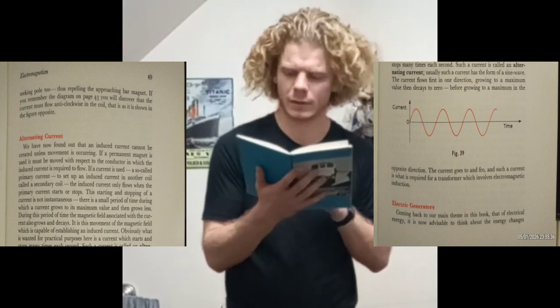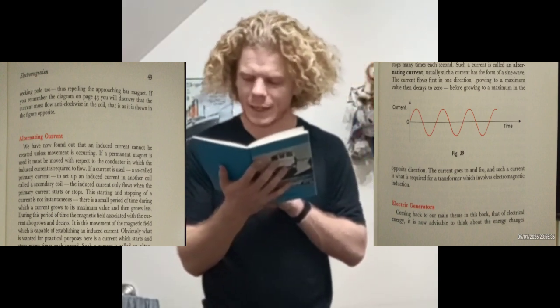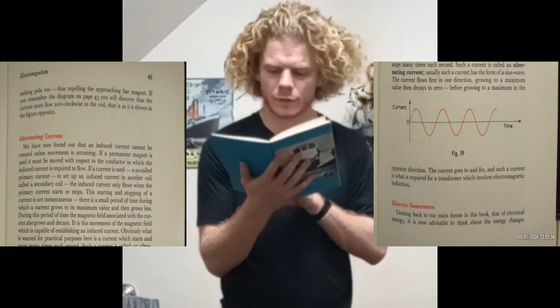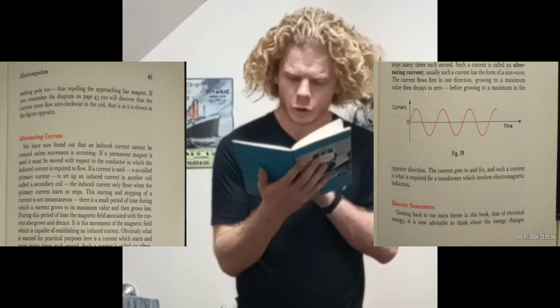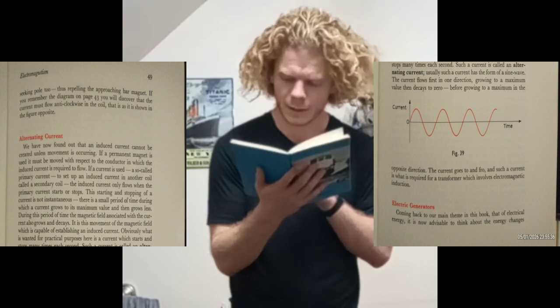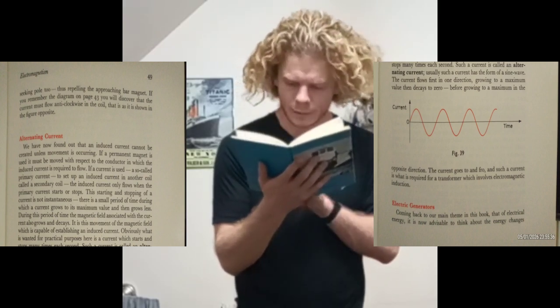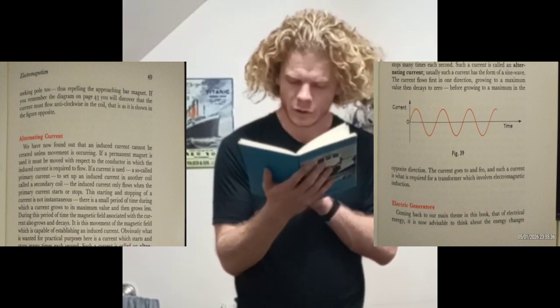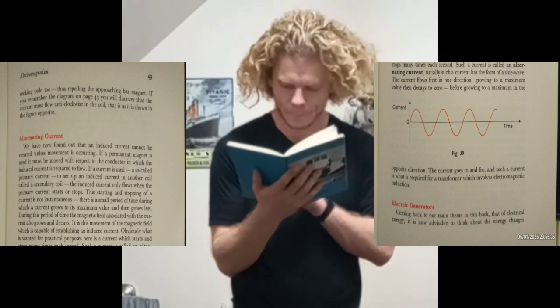But why? Faraday's experiment involves, of course, the basic principle involved in the transformer, which will be considered in a later unit in the series. You should now perform further experiments to supply more information on the rather puzzling starting and stopping aspect of an induced current. You will need a coil of many turns of wire, 100 or more, connected to a sensitive galvanometer.